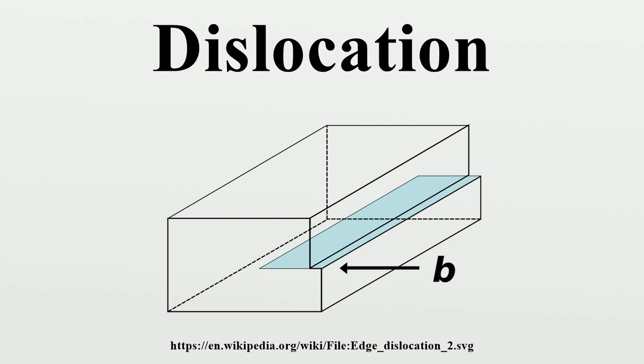The effects of strain hardening by accumulation of dislocations and the grain structure formed at high strain can be removed by appropriate heat treatment, which promotes the recovery and subsequent recrystallization of the material. The combined processing techniques of work hardening and annealing allow for control over dislocation density, the degree of dislocation entanglement, and ultimately the yield strength of the material.